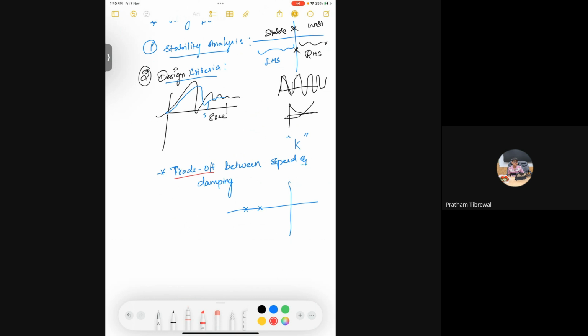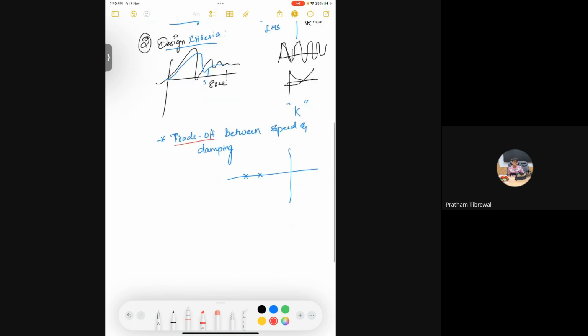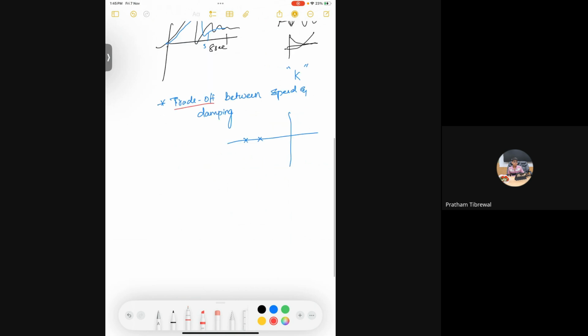In order to find stability every time by using a Routh-Hurwitz or any other method, instead of doing all those things, we can straight away use this method to check the trade-off between which will be the optimal position, so that my system would be stable and also give the desired output specifications or desired transient responses. So I would get to choose based on this root locus analysis.